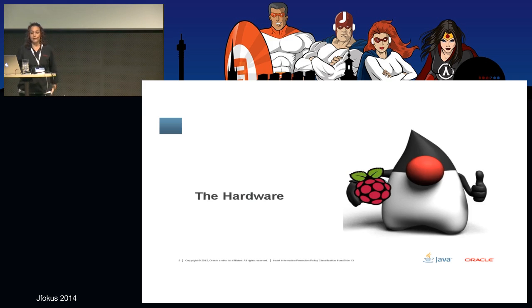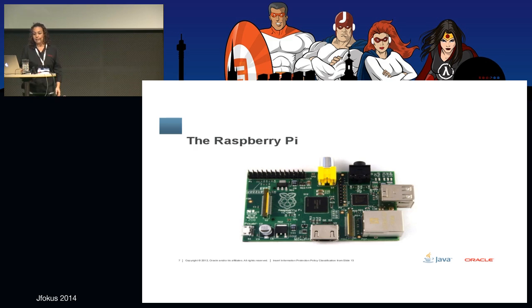Okay, so the Raspberry Pi, big picture, everybody knows about it. I love it. The important thing to notice here is we have a set of pins that we can see there, and that's where you actually end up connecting things. So the Raspberry Pi has GPIO access. You can do SPI, I2C. You get voltage, you get ground for those pins.